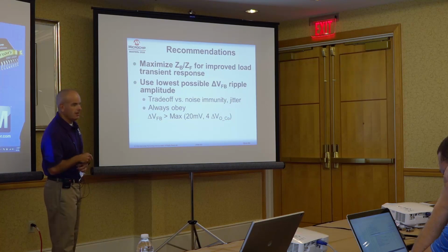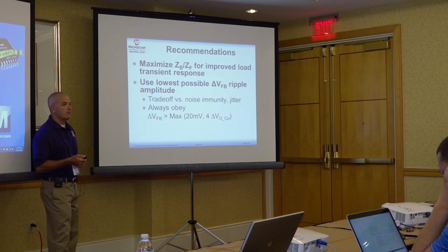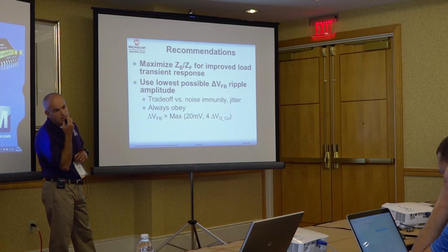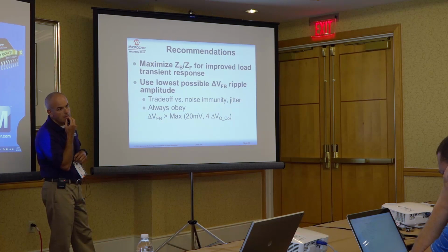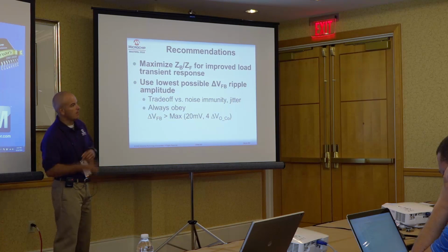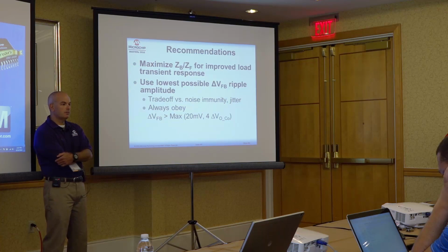The same question for the value of the output capacitor. Disregarding that we choose the output capacitor for a minimal ripple or something like that, is the value itself affecting transient? The value of the output capacitor does not affect the transient. On the inductor, we have seen some limitation above a certain value, like 15 microhenry.